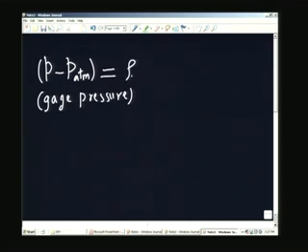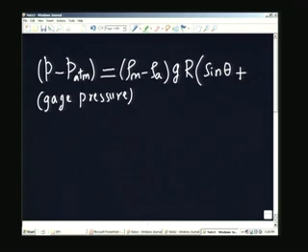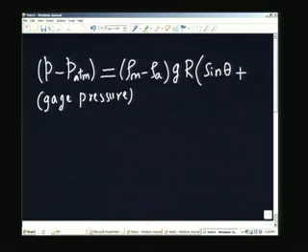rho m minus rho air, or rho fluid in general, multiplied by the gravitational constant g, multiplied by the reading. There are two factors inside this. One is because of the height which is measured, which is actually r times sin theta. So, I will put the sin theta here, plus the depression of the level within the well, which is calculated based on the incompressibility assumption. Sin theta will not come there. Therefore, this will be simply the area ratio here.